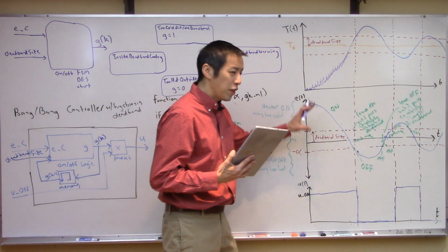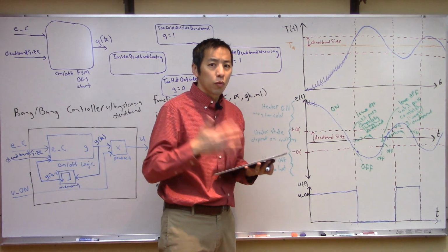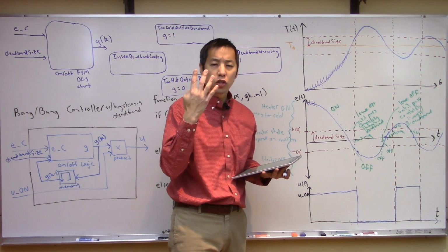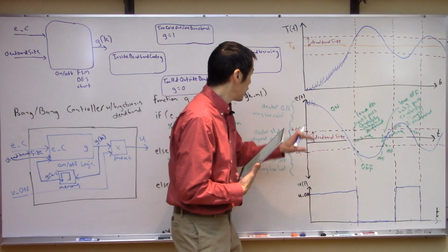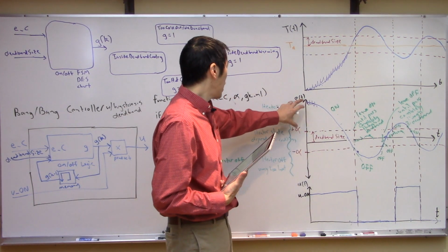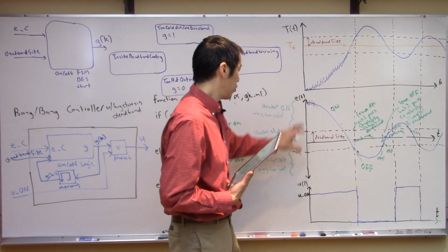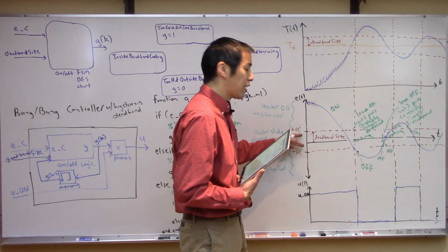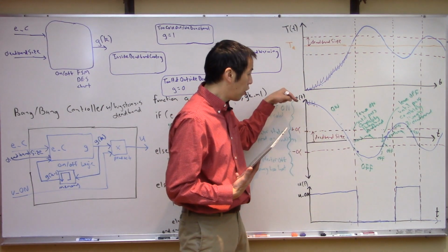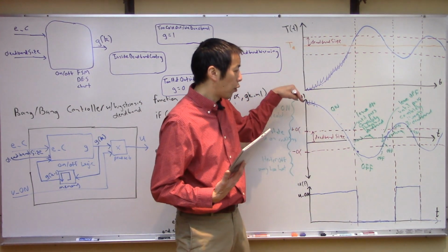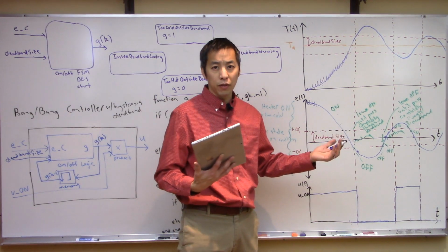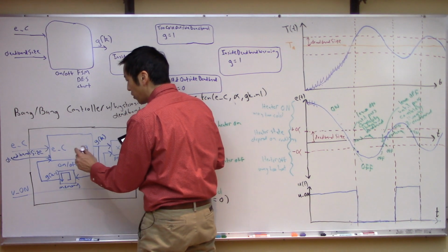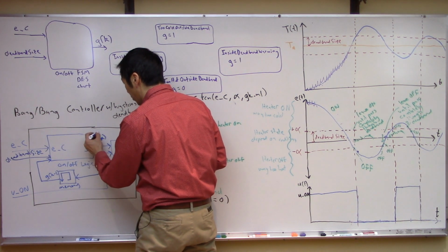Okay, so if you think about this whole logic that we're discussing, really the controller can be in 4 different discrete states, right? You're either way too cold and you turn the heater on, or way too hot, so you turn the heater off, and then inside the deadband, there's 2 states. You're either on the downswing or the upswing for warming or cooling, respectively, right? So there's 4 states.